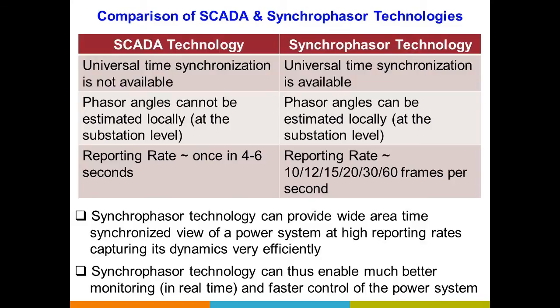And lastly, because the synchrophasor technology can provide us these kind of benefits, that enables much more efficient monitoring of the system and hence faster control of the power system. It is this technology which has the power of most probably even preventing blackouts. So in the future, with more deployment of PMUs and PDCs, our power system can become even more secure and reliable. That is the power of synchrophasor technology.